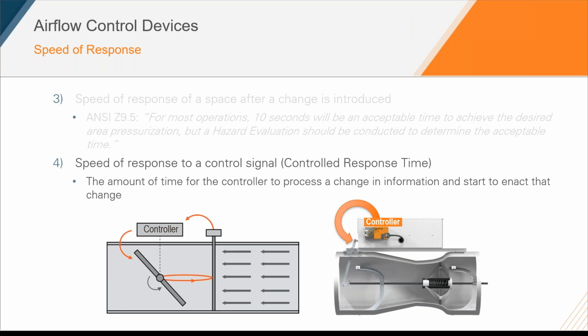On the opposite end, for the venturi valve, the mechanically pressure independent valve, this is going to be a lot faster due to the fact that when the actuator adjusts, we essentially are just controlling the lever arm position to the predetermined factory defined set point.